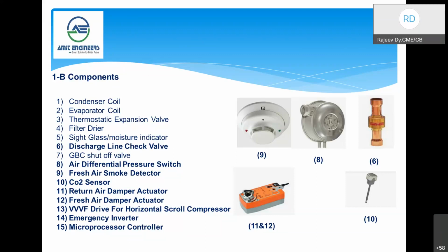Actually, for this capacity, currently Emerson doesn't have any vertical compressor. That is the availability; based on the availability, we have given horizontal compressors. So what is the most suitable, the vertical or horizontal one, as far as displacement, durability or maintenance is concerned? The horizontal will occupy less space, but once Emerson comes out with a vertical one, we can provide it in future projects. But the horizontal, definitely, will occupy less height. Okay, fine.